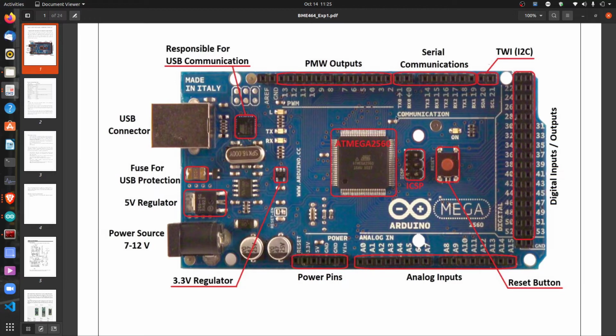This is the microcontroller, the ATmega2560 I told you about, an AVR-based chip, which you install the Arduino platform into, and then you can program it with Arduino. Before you program with Arduino, you just have to install the bootloader into it, and then it will allow you to